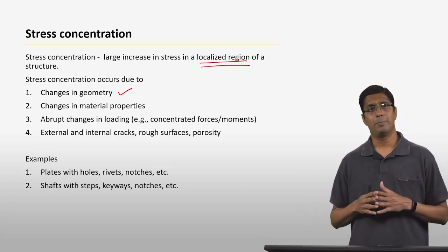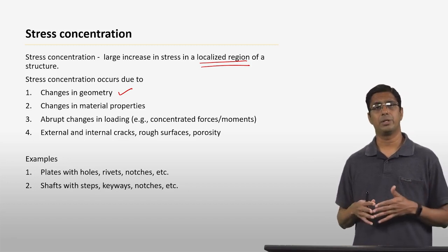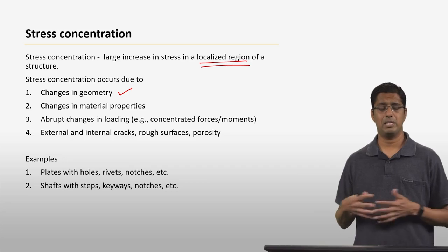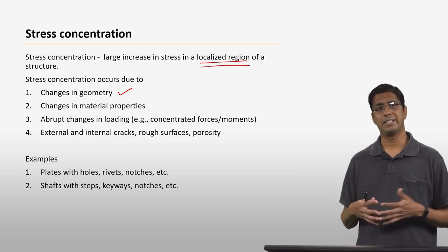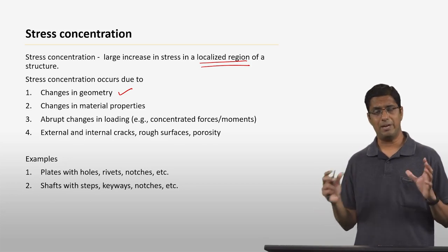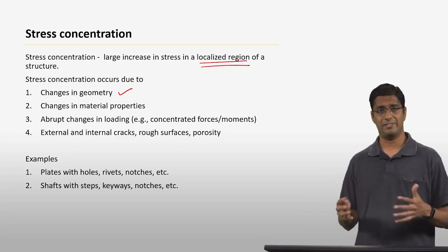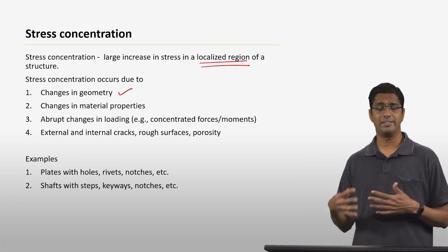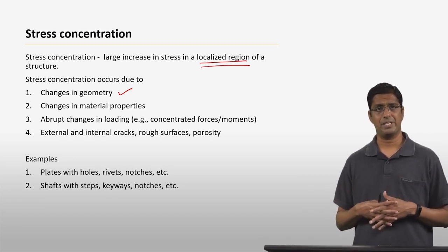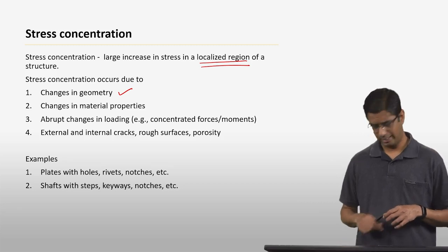So pretty much any structure that you design that is used for a practical purpose has some stress concentration. The idea is basically to either analyze these things properly so that you can have sufficient factor of safety, or you make changes in the design so that you can reduce or mitigate the stress concentrations. Okay, so we'll look at a little bit of both in the following.